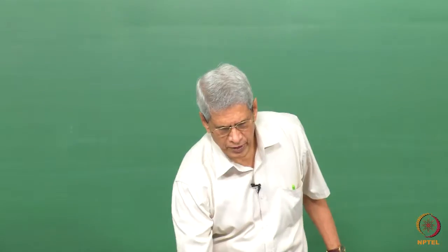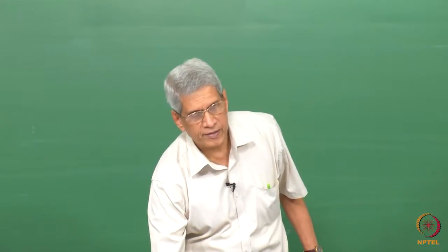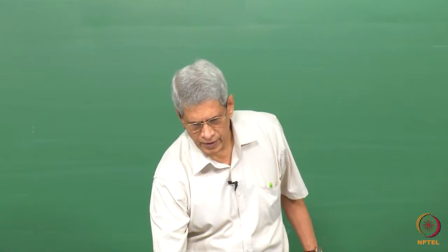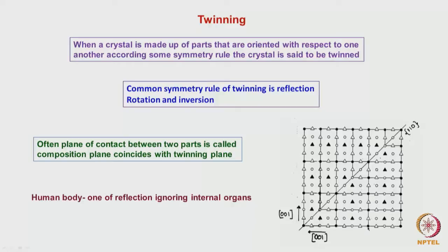That is precisely what is being shown here: here the c axis is in this direction, in this one the c axis is in this direction. Then across the interface you see that they are related by twin, as if this whole unit cell we had given a shear and deformed it homogeneously to bring it from this structure to this particular structure. This aspect of it we will now consider.